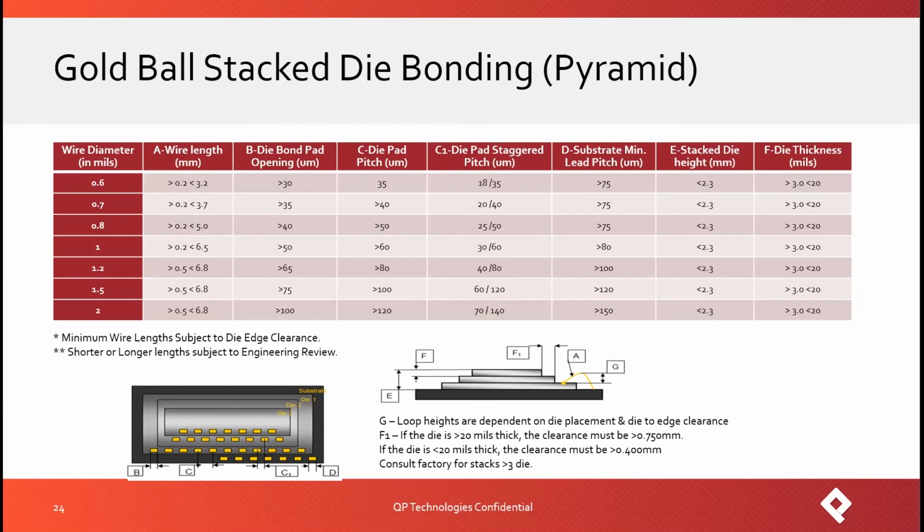One of the questions that has come up in recent time and happens in chip on board often is wire lengths. Our tools, as most tools, have a physical limitation as far as spool out of wire of about 6.5 millimeters. We can probably stretch it to 6.8 or maybe even 7 in worst cases. Occasionally, we will use jumper wires for extra long wires as a way of mitigating this constraint.